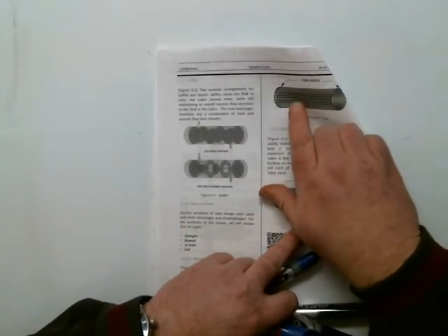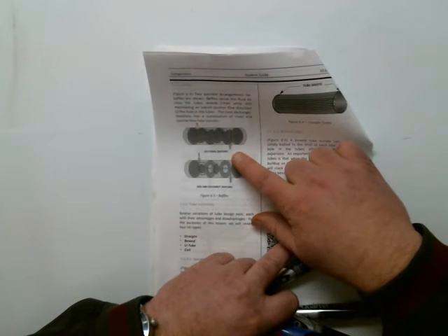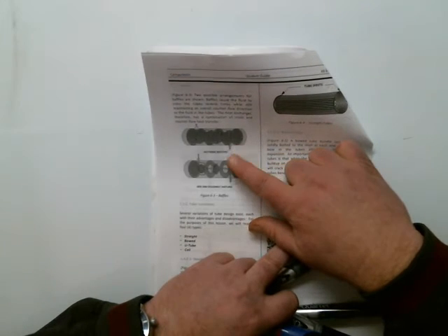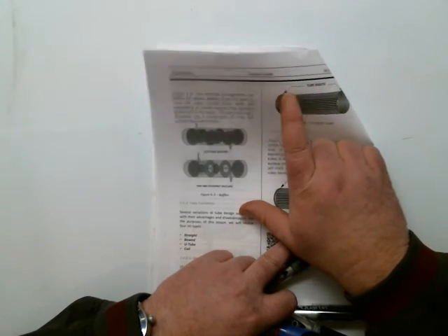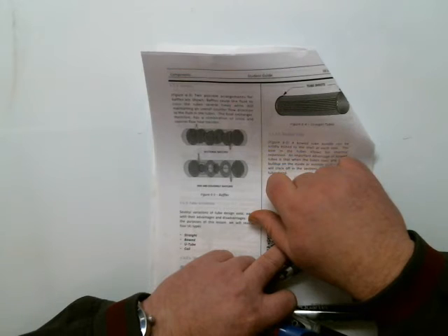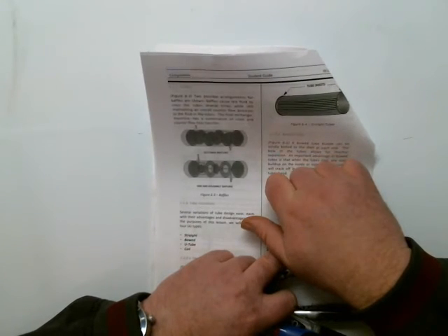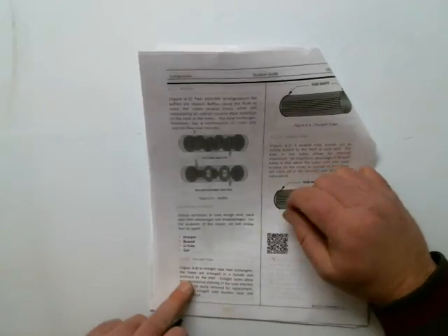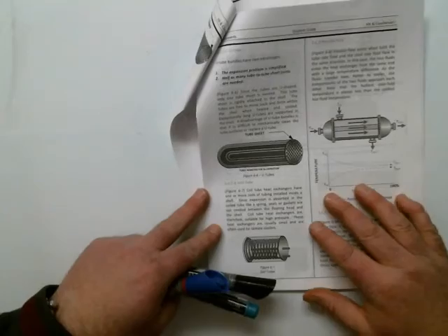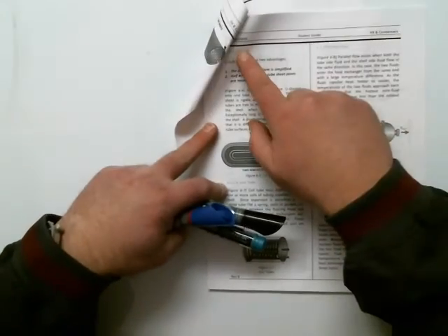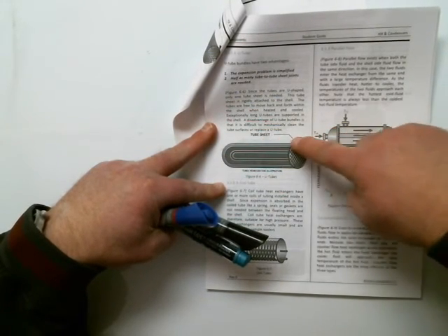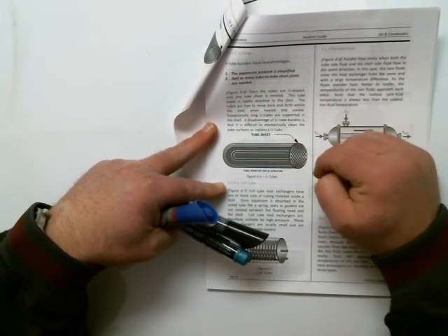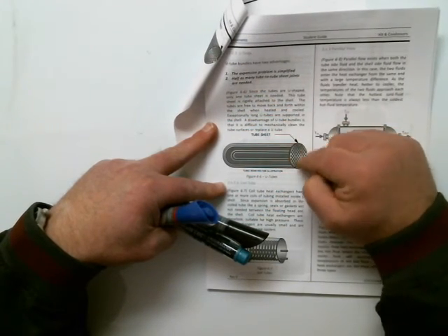Probably predominantly your heat exchangers will be straight tube if you go look at feed water heaters and turbine building closed cooling water or reactor building closed cooling water or whatever. A good portion of your heat exchangers are going to be straight tube heat exchangers. The last two that we look at here, we could have a U-tube heat exchanger. In a U-tube, flow comes in, goes around and comes out, and there's only one tube sheet. That's an advantage.